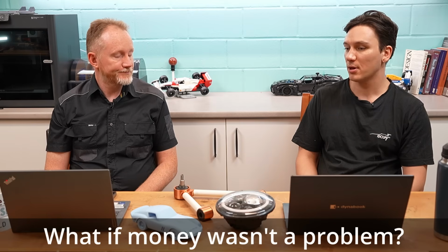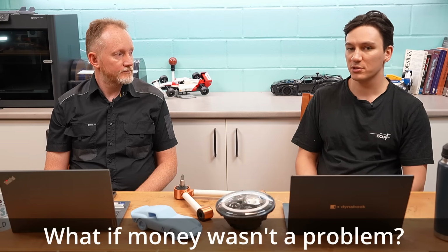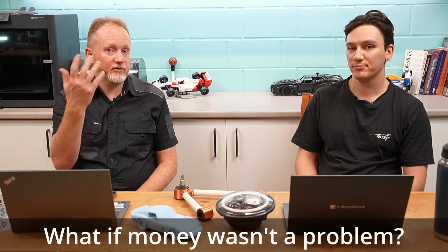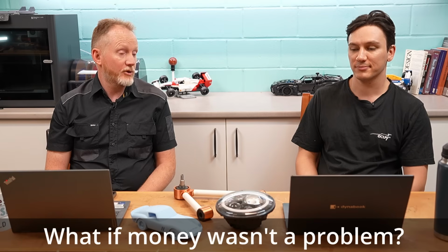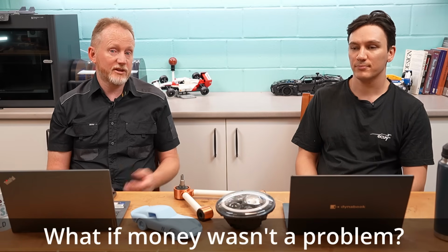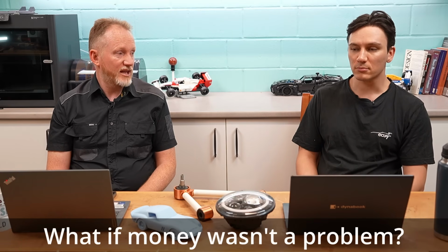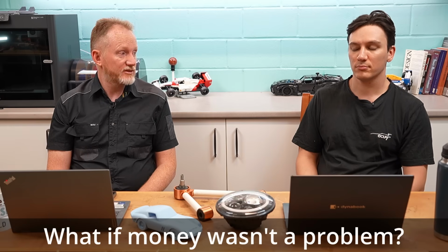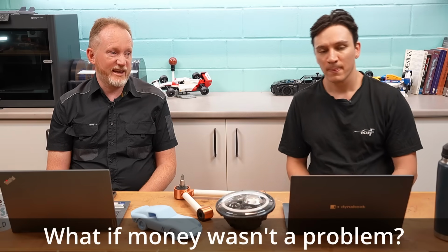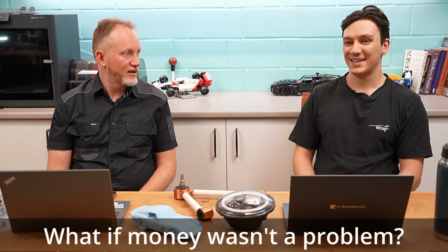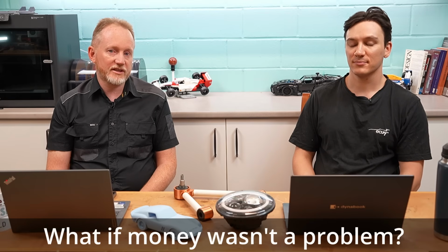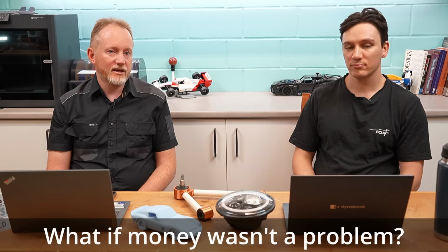Yeah, money can buy you convenience. For example, you could pay designers, but at the end of the day, if you want to design a sports car yourself, it doesn't make sense to pay someone to do it for you. If you look at an upright, we're probably going to make the upright and the suspension out of billet aluminium. A billet of 6 series aluminium is not that expensive. Even 7 series is not that expensive anymore. And if you really want to, you can machine that stuff with a hand router. It wouldn't be fun, but you could do it. So the material is not going to cost you. It's actually the equipment and the processes around that.